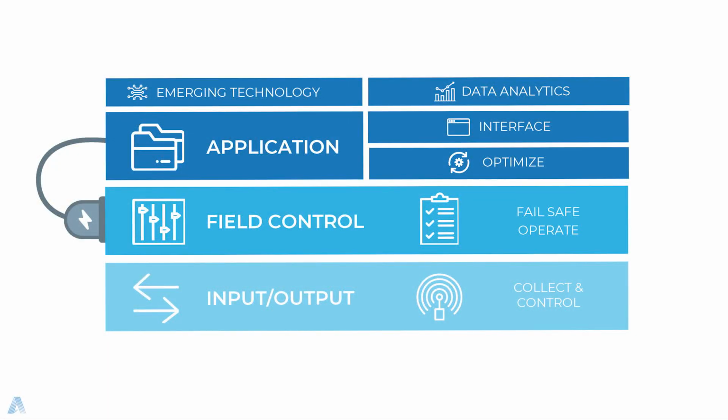So we can have optimization live up in that layer as opposed to distributed across all these different projects where you might get a different interpretation of how to optimize from a Distech provider to a Siemens provider to a Johnson Controls provider, et cetera. So we standardize that. We make it a lot simpler now for those field level systems to be implemented because we're pulling a lot of that complexity of things like ASHRAE Guideline 36 out of their scope, and we're managing that at the enterprise level.